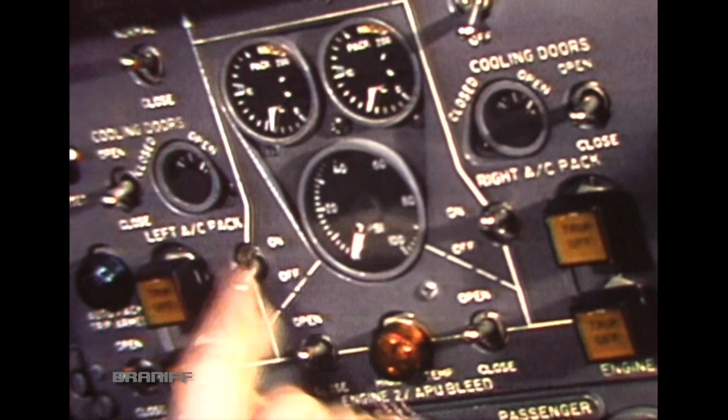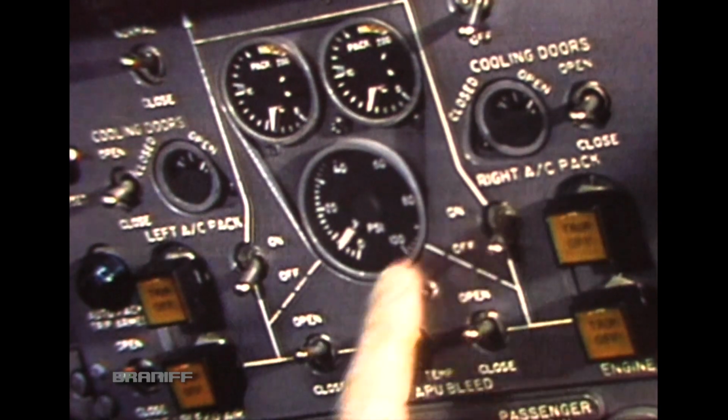Do not spray fluid directly at or into pitot inlets, static ports, TAT probes, engine and APU inlets, or other openings. If necessary, engines and APU may be operated while anti-icing or de-icing. However, the cabin air conditioning pack valves must be closed.